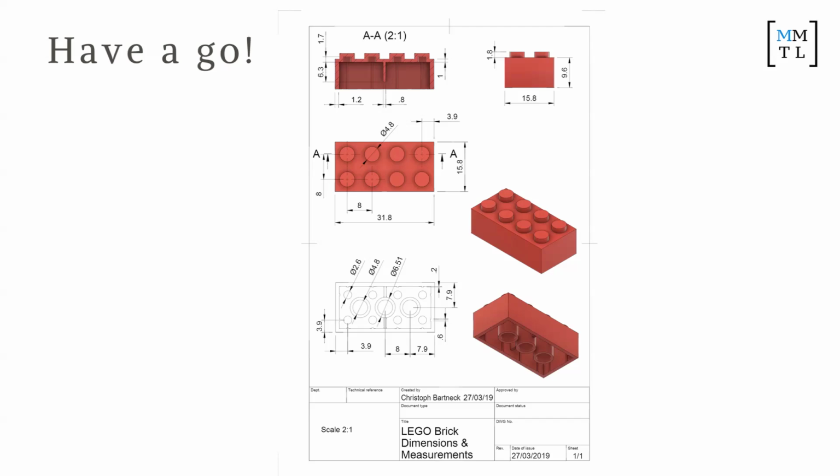Okay, sketch my circle, right? So my protrusion circle. For those at the rectangular pattern stage, well, I just gave it away, but in the pattern stage in the top bit, instead of extent of the distribution, you can use spacing. And then you can use the dimensions given, so 8 and 8, that way you can create the spacing, and then you know it's 4 and 2. Yeah. So it should all work out very nicely.